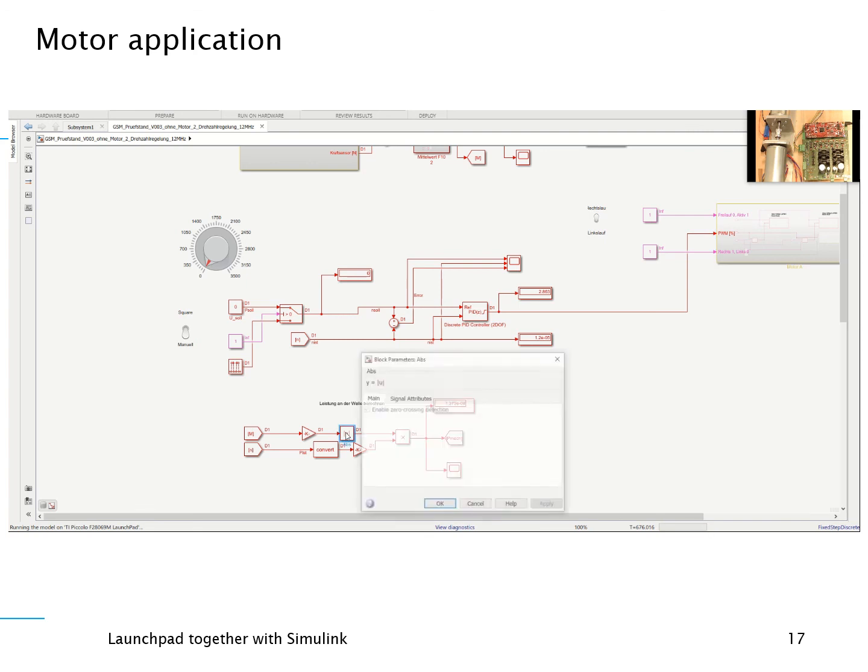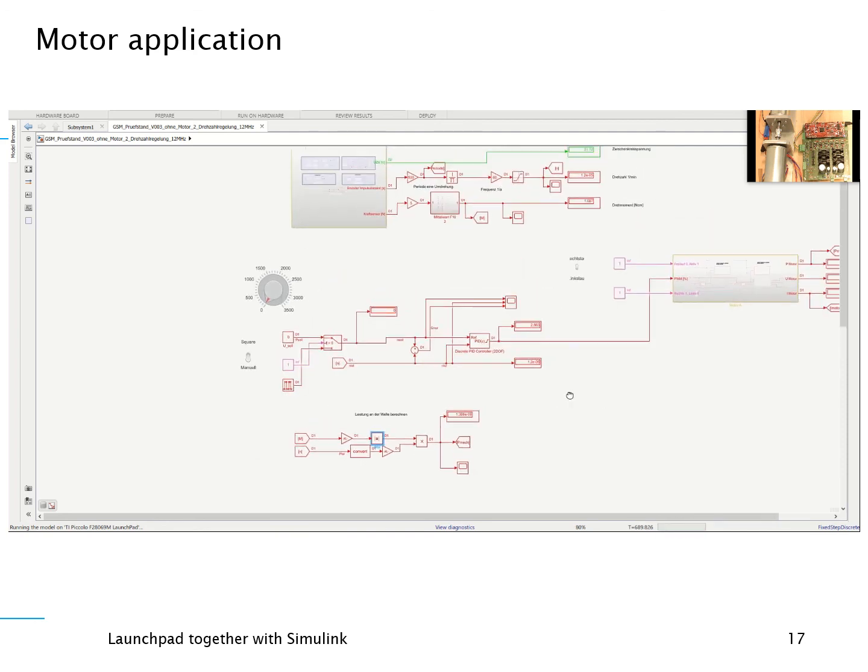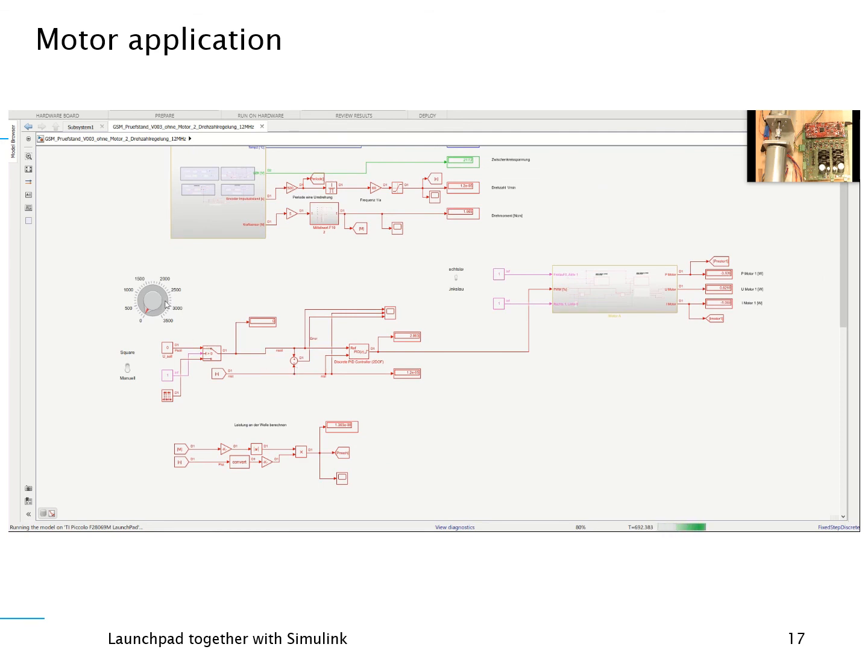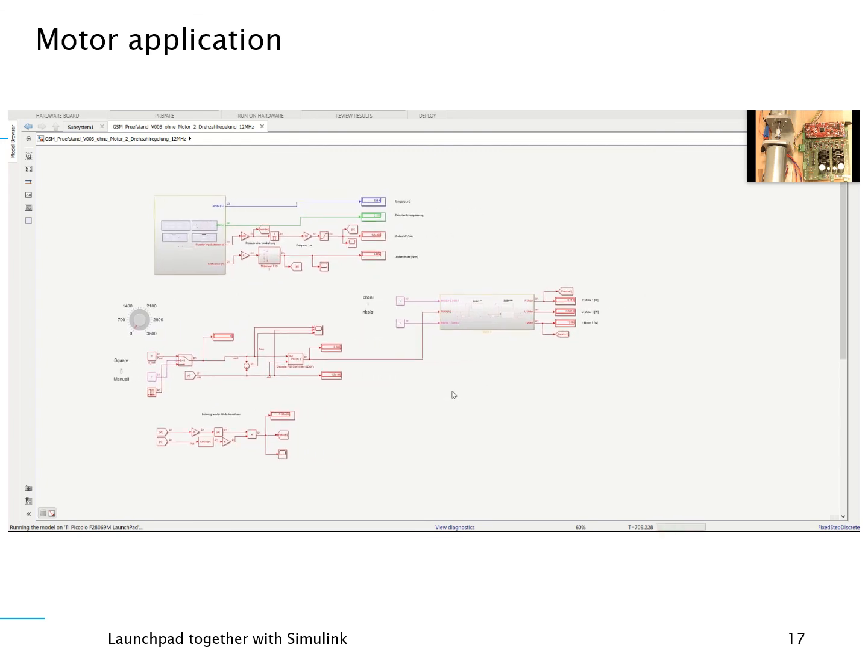Here we build the absolute values and so on, like you are used to with all your other problems you have calculated with Matlab Simulink. There is one drawback: of the dashboard blocks, only the knobs or switches are working. Unfortunately, we cannot use dashboard scopes if we connect to the hardware. And that's all. That easy it is.